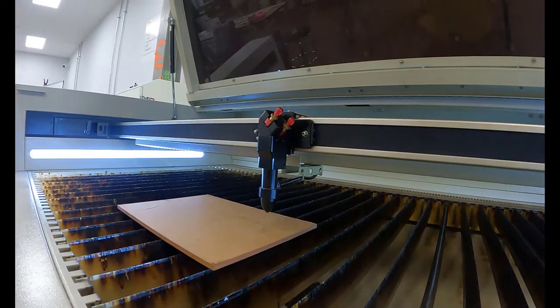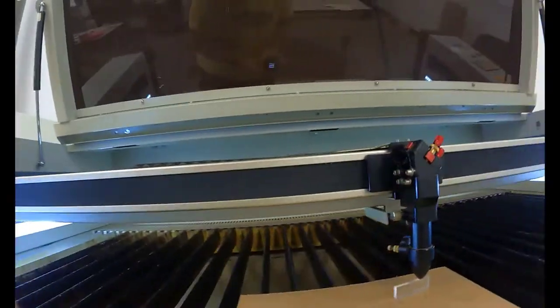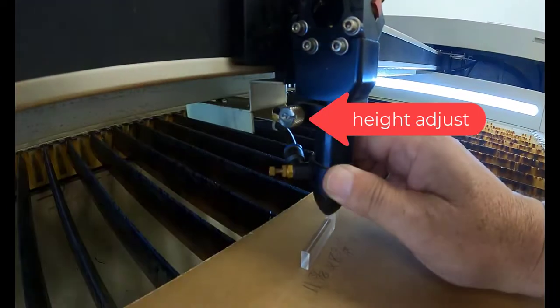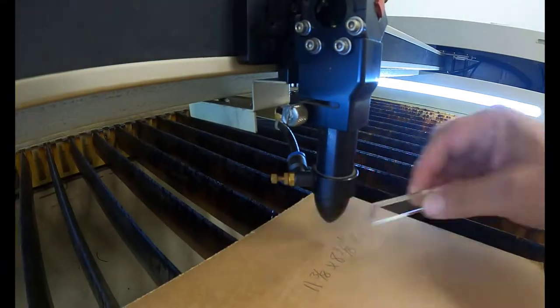Before we cut on the large laser cutters, we need to calibrate the laser, and that's done by using a spacer and manually adjusting up and down. On the small laser cutters on the other side of the lab, autofocus will automatically zoom in and zoom out.